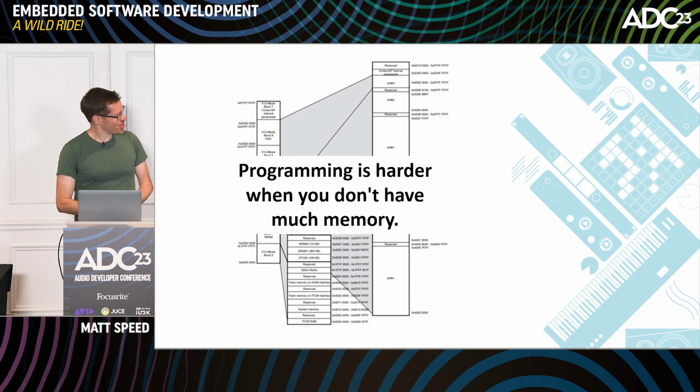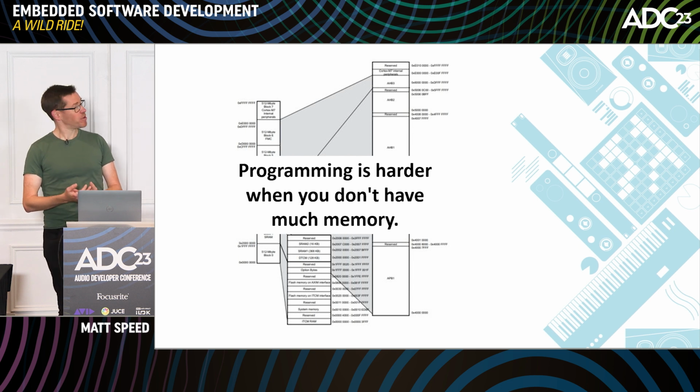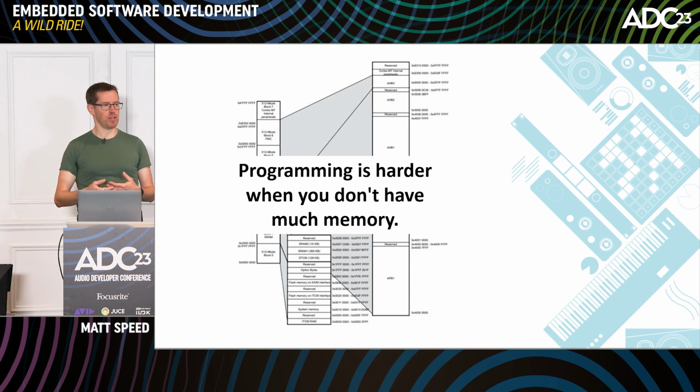But also, you work in linker scripts, so you'll be very, very careful about how you use the memory. The linker script tells the linker where this stuff is, how it can be used. And then the linker map, it gets spat out by your linker, tells you what you're using for what, which bit of your binary is using how much memory. That's important for figuring out afterwards what you did that suddenly consumed all of your RAM.